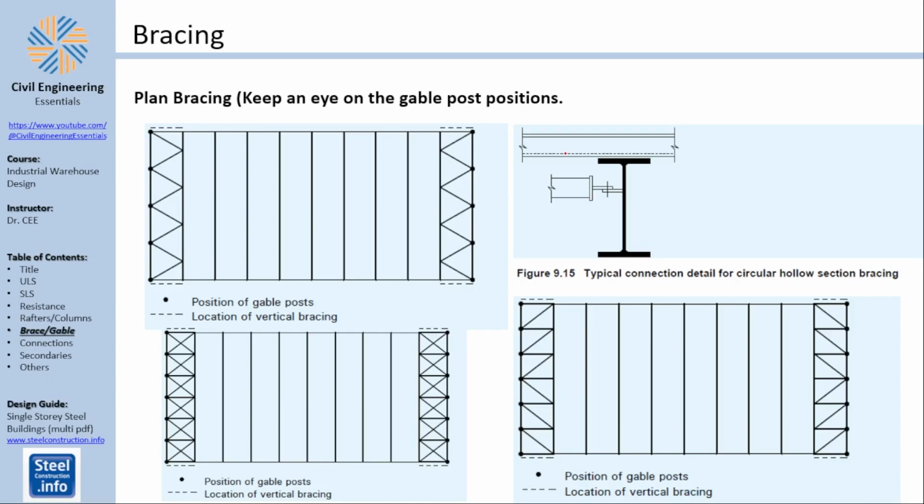How are those bracing used? Those are usually hollow tubes being connected like this to a column. This is the external purlin. You can see the bracing being connected to the column, not in the same plane as your external bracing. So offsetting the bracing was actually a correct call we have done before. This is the roof bracing. Notice something important: if you have gable columns, your bracing should connect to the gable columns.